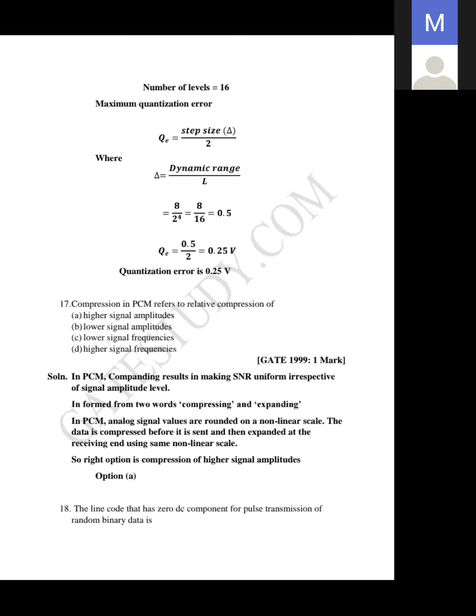In this process we miss certain information, because while converting there will be rounding off of values to the nearest possible digit, giving some round-off or truncation error. Those errors are considered quantization error. That's why when we use digital communication we can't expect the outcome to be 100%, because there will be minimal errors introduced while converting the analog signal into a digital signal.